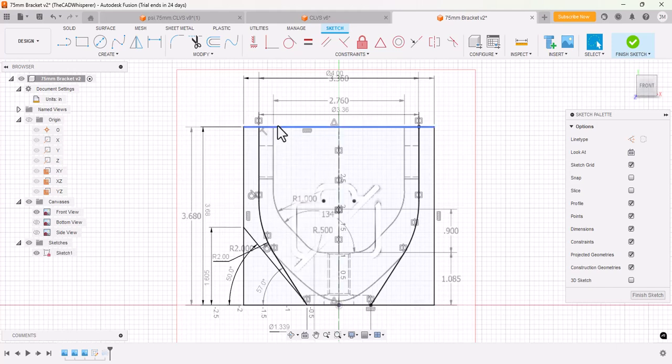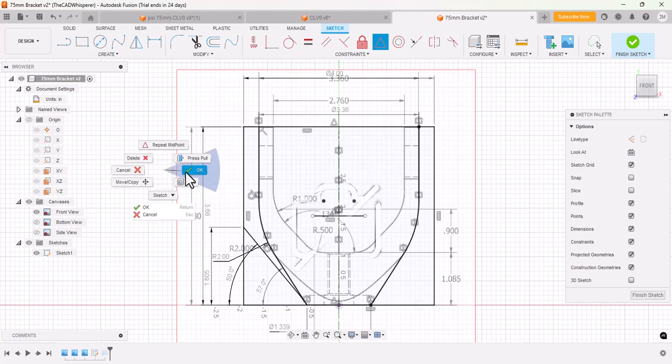and I'm going to then do the inside sketch lines here. And I'm going to start this out with a horizontal line. I'll just put it out here in space initially, and then I want the midpoint of this line. I accidentally created an extra line. I want the midpoint of this line to be over here on this center line. So I'll do a midpoint constraint over onto this line.